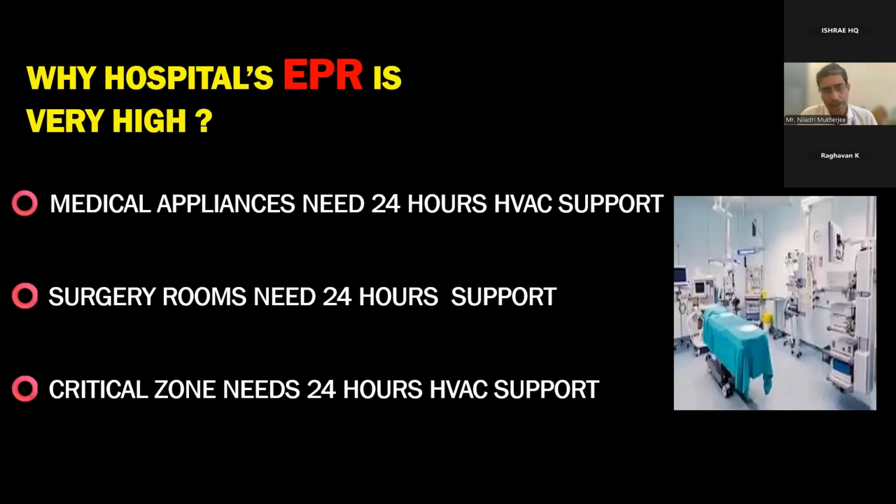You see, green building people may raise objections, and ECBC and the National Building Code have made some guidelines. These cannot be applied in hospital design or to the critical areas of hospitals. Medical appliances need 24-hour HVAC support. The surgery room needs 24-hour support. The critical zone needs 24-hour support.